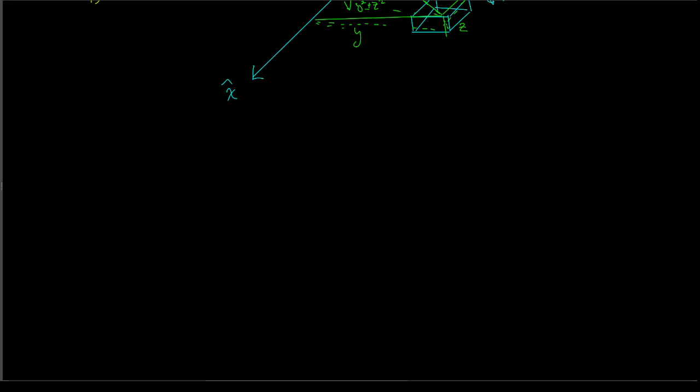Furthermore, if we were going about a line, any line, so I, the moment of inertia about line L, some rotating axis. Remember, rotating axis can be defined by a line. Then it'll be the radius function to that line squared times our dv element.